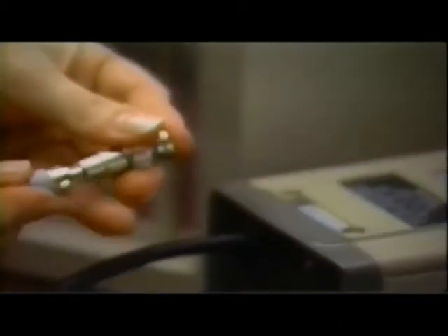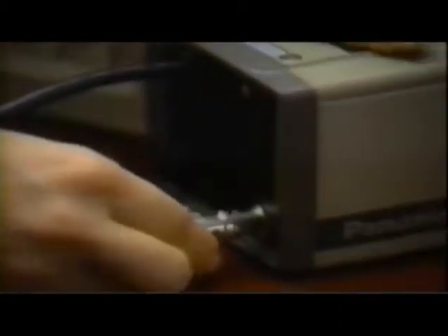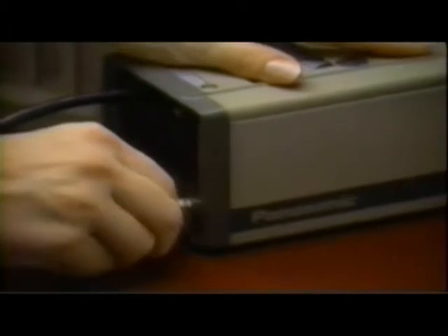The DigiView package consists of digitizing software and a small interface called a video digitizer. An RCA to RCA cable connects to the digitizer. The other end will need an RCA to BNC adapter to plug into the BNC connector on any video camera. An inexpensive black and white surveillance camera, such as the Panasonic WV-1410 camera, will give excellent results.